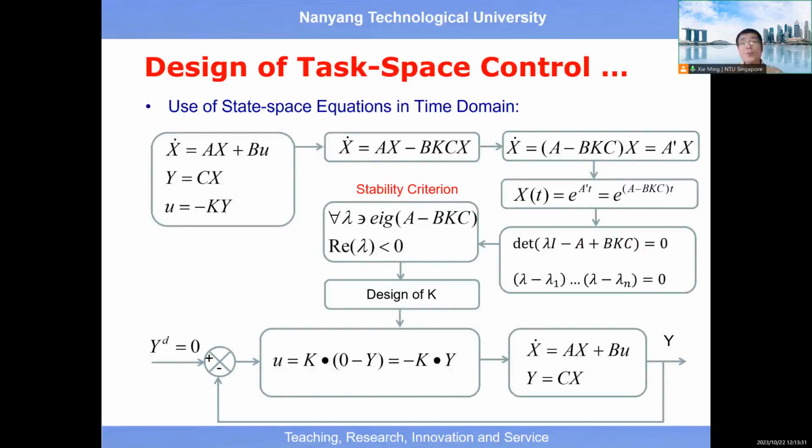Then the next question is, how do we determine the amount of mechanical power to inject into our vehicle in order to control the steering angle, control the linear velocity, all right? So now you see, we just use this philosophy of producing an amount of energy to control the dynamics based on the equation of error. And this equation of error, the error, is the difference between the desired output and the actual output.